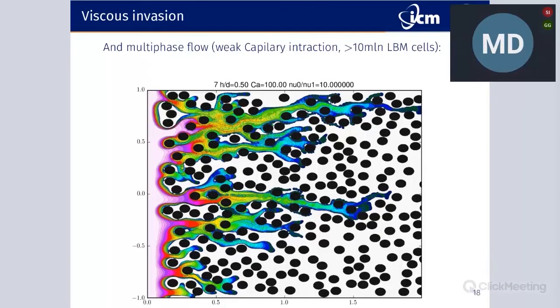So using our numerical tools, you could try to determine the post-breakthrough configuration of the system, the amount of pressure or work needed in certain configurations, and build an upscaled model that could be used to determine properties of the whole rock reservoir.